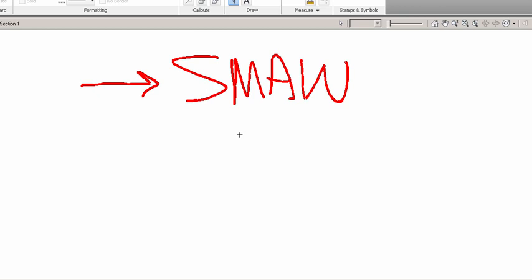But there are some disadvantages to SMAW as well. First of all, while you're welding and you're getting into your groove, you burn through your electrode. So you have to stop and get another electrode and then keep on going. So there's a discontinuation for long welds that can be a problem, especially if you're in an uncomfortable position or in tight spaces, that sort of thing.